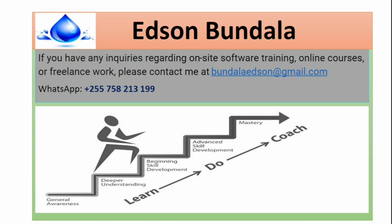Another question people ask me is, sir, is it possible to import a network from an external source? The answer is yes. In WaterGEMS, you can import different source data. You can use shapefiles, ESRI shapefiles. You can use AutoCAD, Excel spreadsheets, and others. There are many. How do we do that?